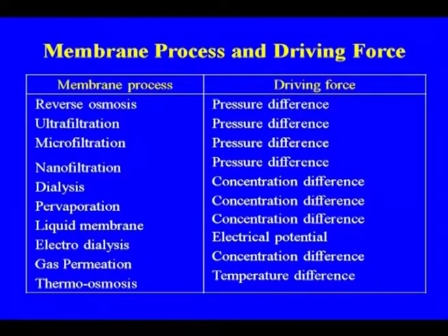Now we will be discussing the various membrane processes. As I told you, there is continuous development in the membrane process, and now we have a large number of membrane processes where the driving forces are different. First, reverse osmosis and ultrafiltration, which have been used from the very beginning, where the driving force is the pressure difference. Microfiltration, nanofiltration: in all these processes the pressure difference is the driving force.